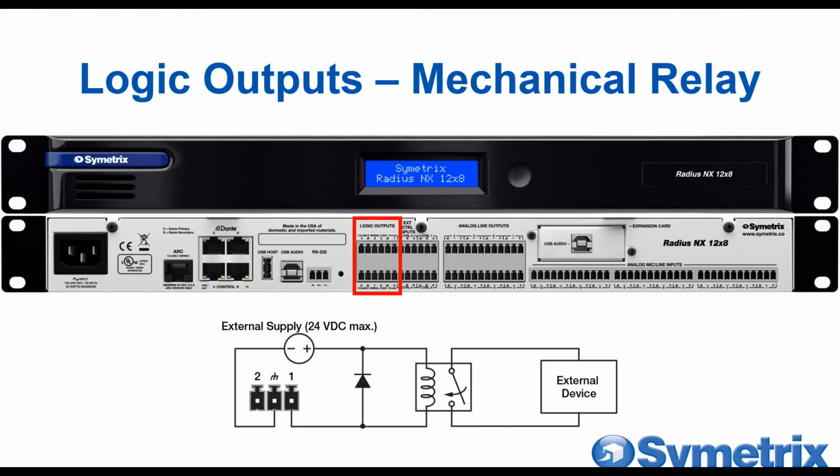Let's look at relays a little bit. You can drive relays, but of course, it all depends on the specs of the relay. Considering the logic output can source 10 milliamps, driving a mechanical relay directly is probably not going to happen. You'd want to use an external supply for that. Again, just make sure that the current getting sunk is less than 50 milliamps. So keep an eye on the coil current of the relay, that's a spec, and do include that flyback diode as well, just to knock out any voltage spikes when you turn off the coil. Without that, you run the risk of destroying the transistor inside the logic output. So always have that.